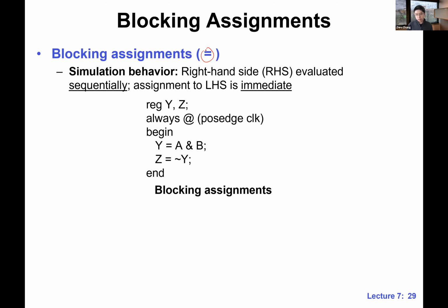With blocking assignment, the statements get evaluated in a sequential way and assigned to the left-hand side, basically the output signals, right away, immediately.